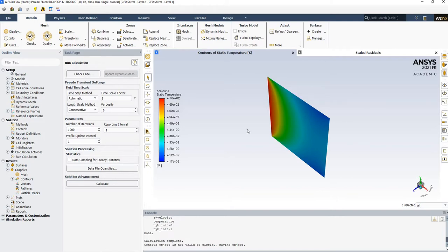Okay. So this is how you can do the surface radiation model. One other thing is, be careful when you specify the emissivity. There are two types of emissivity. One is due to the hot wall body. Another one is due to the surface coating, the incoming radiative heat emissivity. So specify those carefully, and specify the view factor.